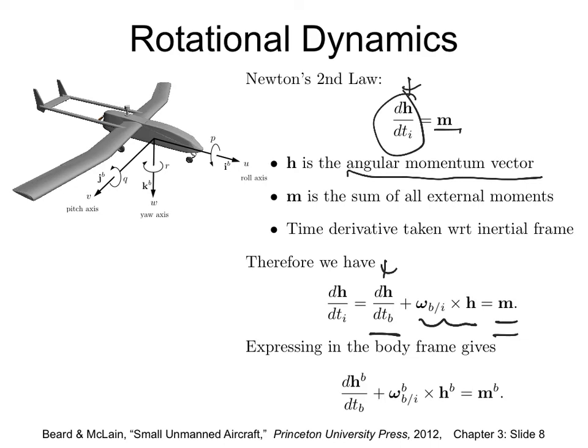But also moments because of, let's say, ailerons. When you use ailerons, there is a moment generated for a roll. Aileron on the different side, moment generated in the other direction. And when you give an elevator on the tail, there is a moment generated like this. So you have control surfaces which are generating moments, and we are using aerodynamics. We know that if I do an aileron up on this side and down here, there will be different aerodynamic forces which will create a movement. So we will incorporate that later.